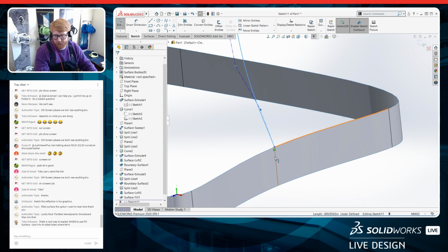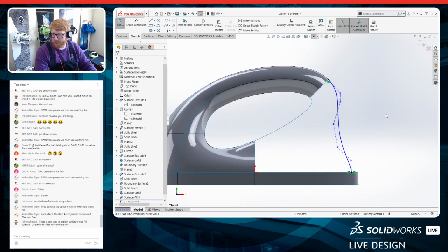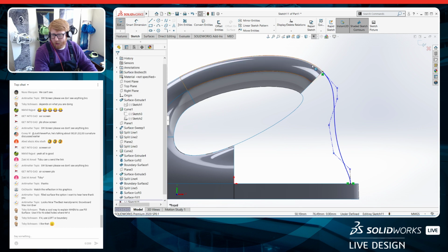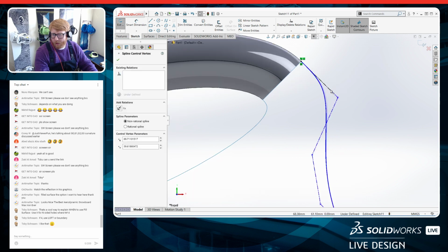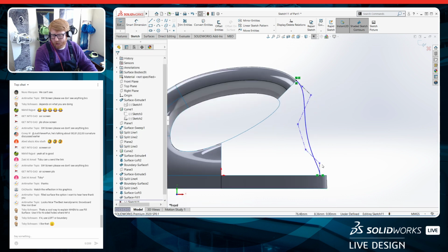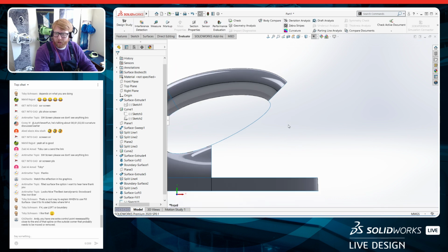And remember, you can't make that vertical. You got to make it collinear because that's 2 degrees of draft right there. You always got to be cognizant of that. And I know that I need this. This basically drops off almost immediately. Something like that. And gets a little tighter up there. Yeah, I think that looks good. Call it a day.